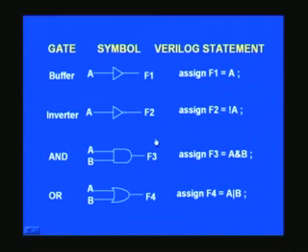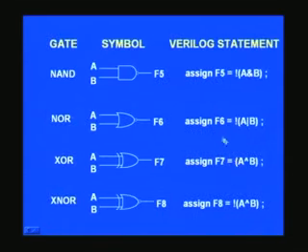And you want to do AND or OR with two inputs. It's once again as simple as that. What you need is one more symbol you have to know. It's an ampersand and this vertical slash here. This is for OR, this is for AND. And likewise, whatever gates you have already derived, you can get its inversion.